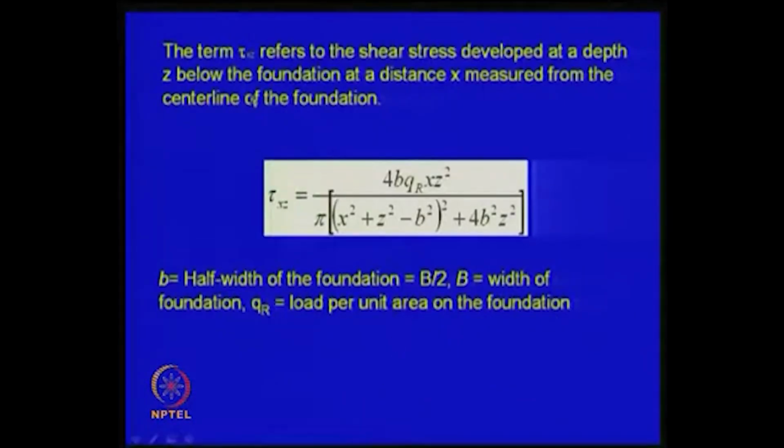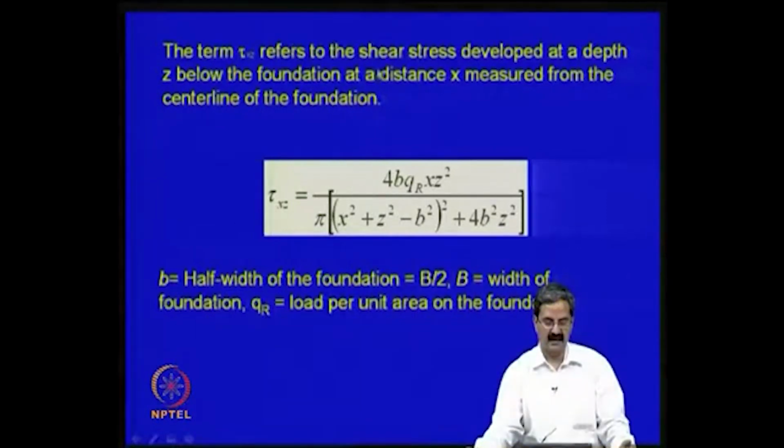As I just mentioned, the elastic shear stress distribution is used. This is an expression that we have in theoretical soil mechanics, and if you know x and z, and b, which is nothing but the half width of the foundation, and qr, the load that you are expecting on the reinforced soil, then you can plot this. It is simple.